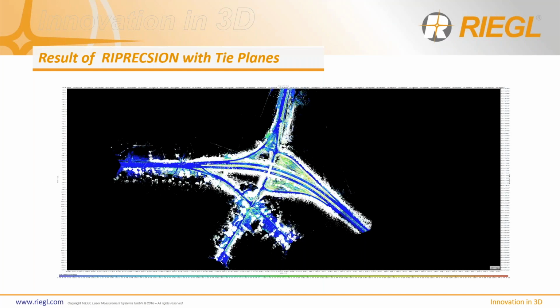So how good was RIE Precision this time? Well, pretty good, to quote Larry David. As you can see here, we have dark blue everywhere. I adjusted my scale so that anything under 2 centimeters of deviation was blue. So we have really great blue data along the main trajectory lines on the highway, as I would expect. There's some fuzz in there from car noise, maybe some shots from the overpass, a lot of things that we can crop out from a range standpoint before we do the final export.